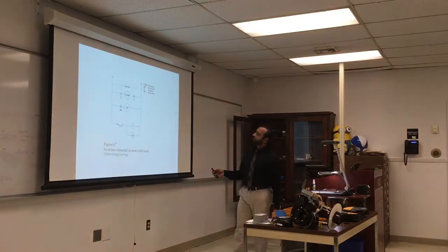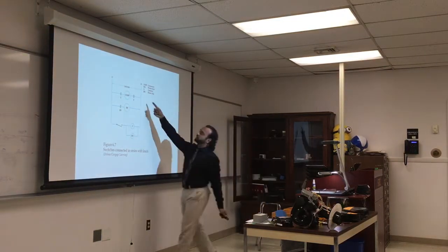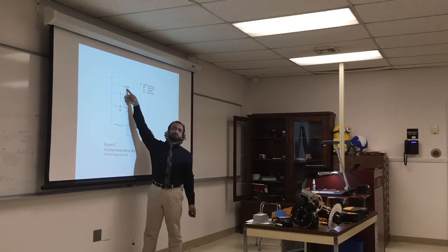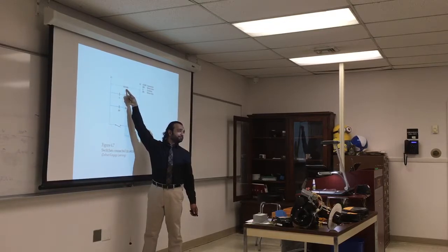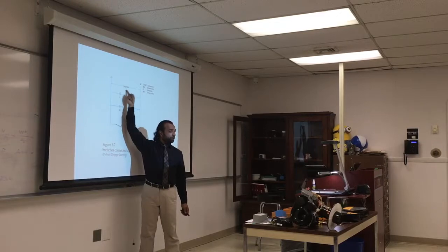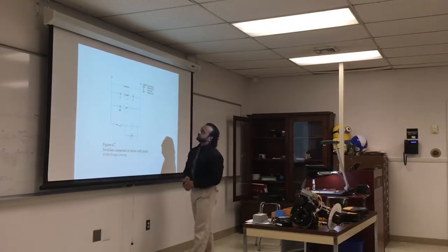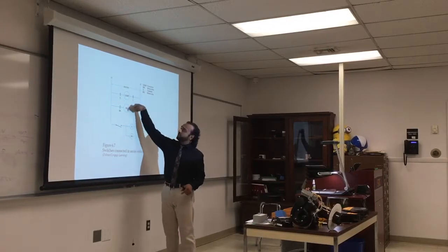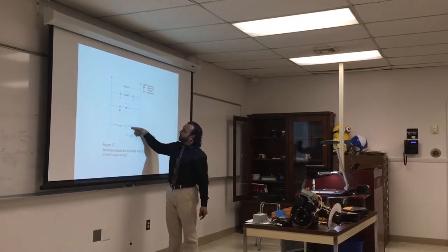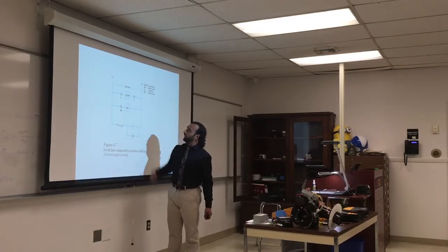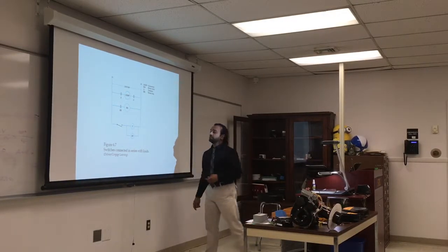Compressor, fan motor, contactor, power relay. Again, what is the voltage here? 240. What is one? One phase. We'll learn about that next week. 60 hertz. What is 60? 60 hertz. We will learn how to decipher this line to know how much voltage should go into that AC. Again, these are in parallel or series? Parallel. What about these two? Parallel. So these are all in parallel. Switch is in series.